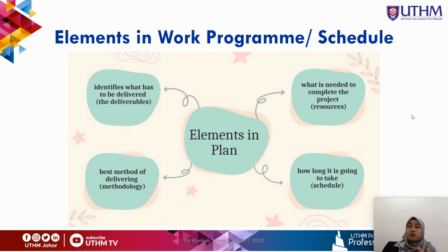So basically, you have to know what the methods are because they will affect the time. For conventional construction, you have to install your formwork and your rebars, do the concreting, and then put on the brickworks and so on. It might take a longer time to complete and lots of resources, but it is the cheapest method of construction, though it depends on the duration. If you've been given, let's say, 1 year to complete the project, it's impossible for you to use the traditional method to complete a 15-story apartment building.